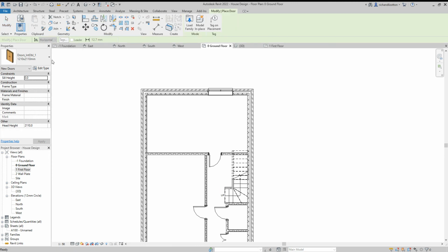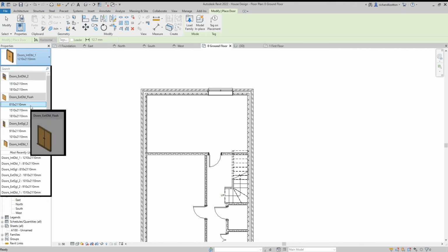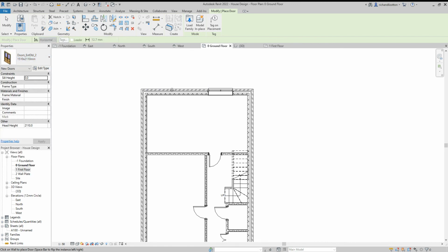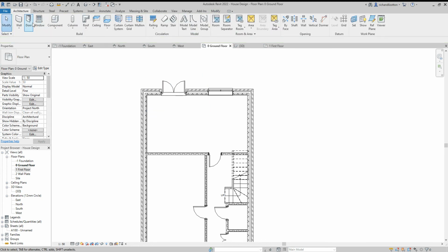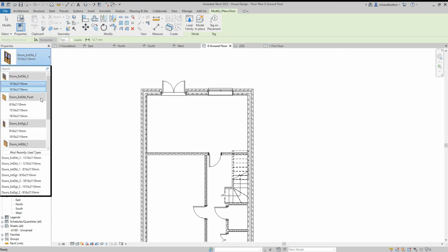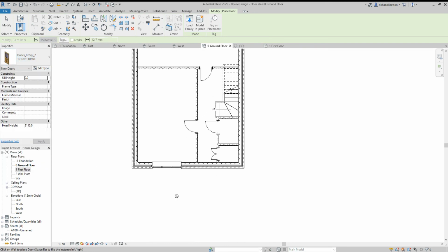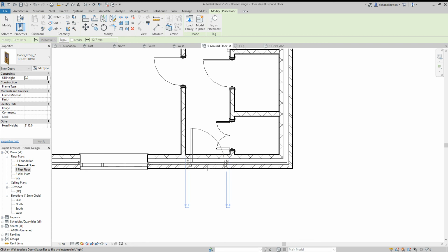And of course, let's put some external doors. See what we've got here. I will use this set by here. And again, do I want them opening in or out? And then a standard door. There we go, similar style. And again, you can use the load family to find more types of door.